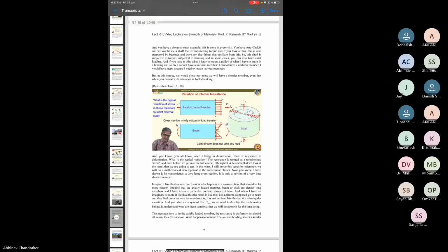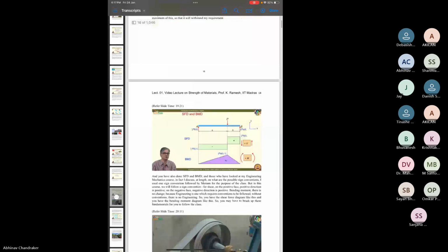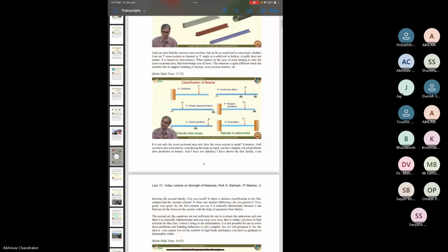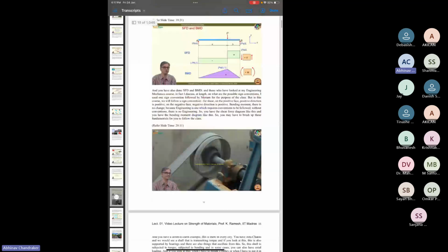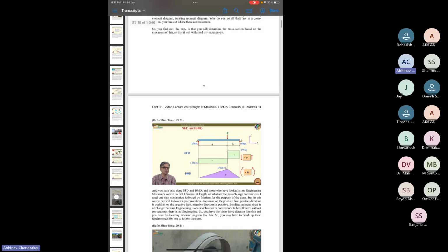So, sir explained how the stress experienced by a cantilever or a beam when it is loaded was discovered over the years. It will have both a bending stress, bending moment, as well as shear stress, and because of that, understanding the stress state in this beam when it is loaded from one end is not trivial.